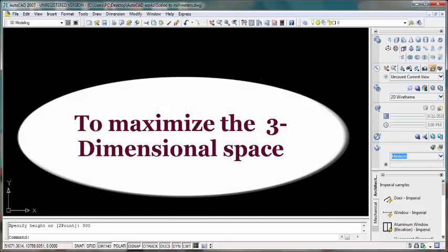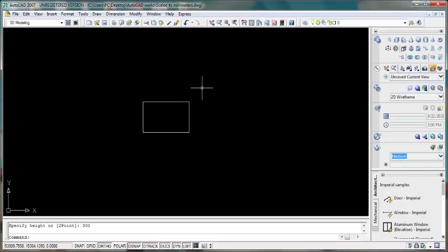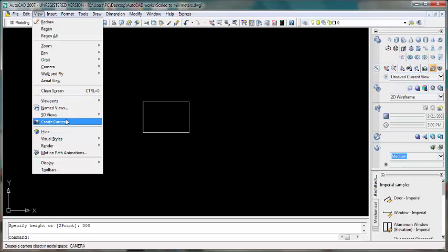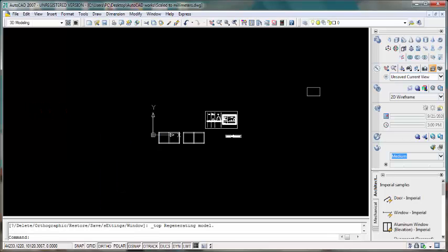Now what you're looking at is a box, but how can you tell? This is just a top view. How do I know? Come to this place, View. Under View, you get to 3D views. Click Top. This is our box.